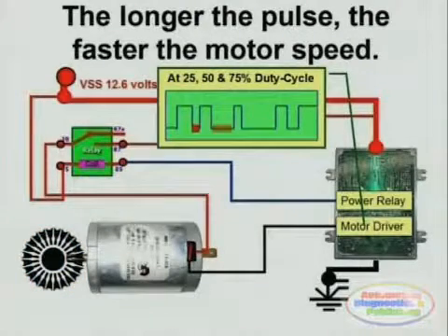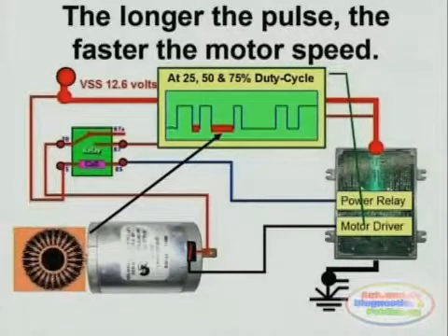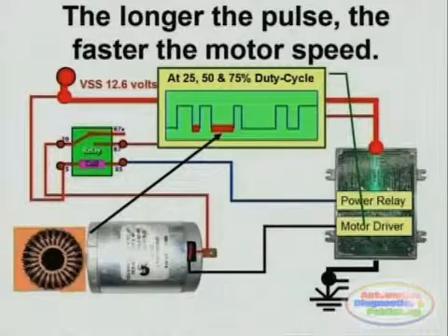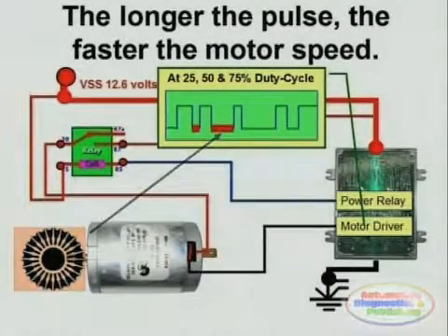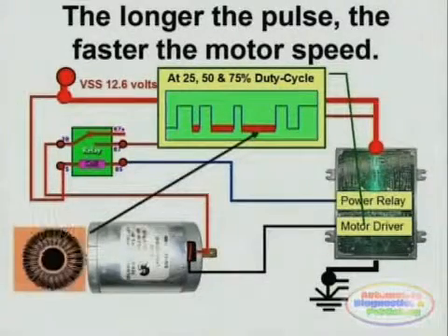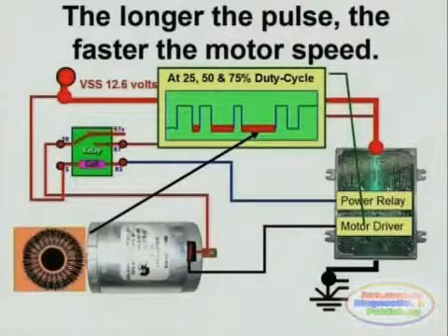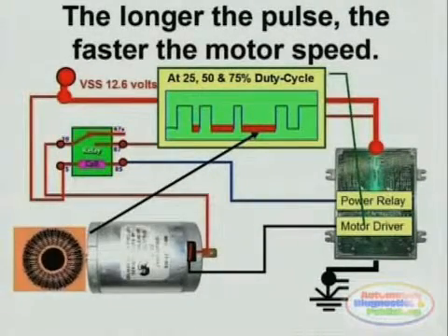At cruise speeds, for example, you will need maybe a 50 to 60% duty cycle for the fuel pump, and this we can see on the screen. And during extremely loaded conditions, such as when towing, you will need maybe a 75 to 90% duty cycle, making the flow of fuel through the fuel rail a lot higher.